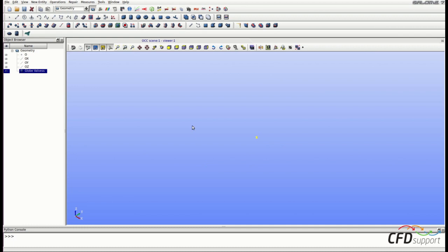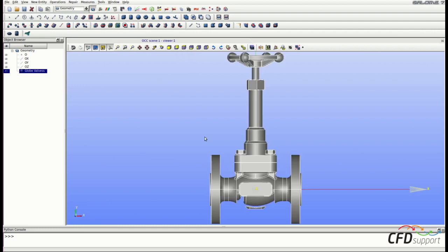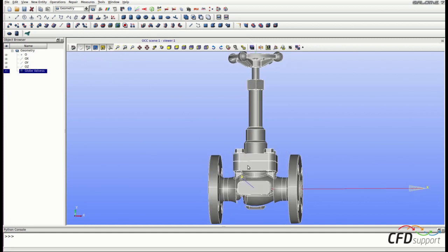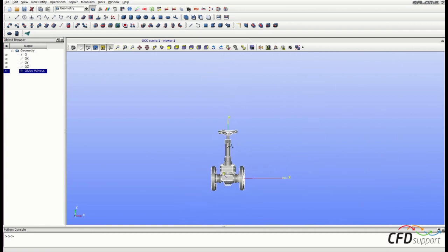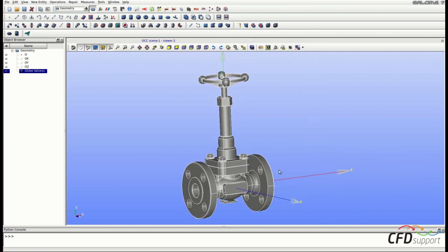It's here, and now click on one of the principal views to quickly zoom the geometry. Now you can activate the interaction style switch to be able to rotate, zoom and move the geometry by mouse. The whole geometry is in one piece now. To process it, we would need to work with just smaller parts. So let's explode it into smaller parts.